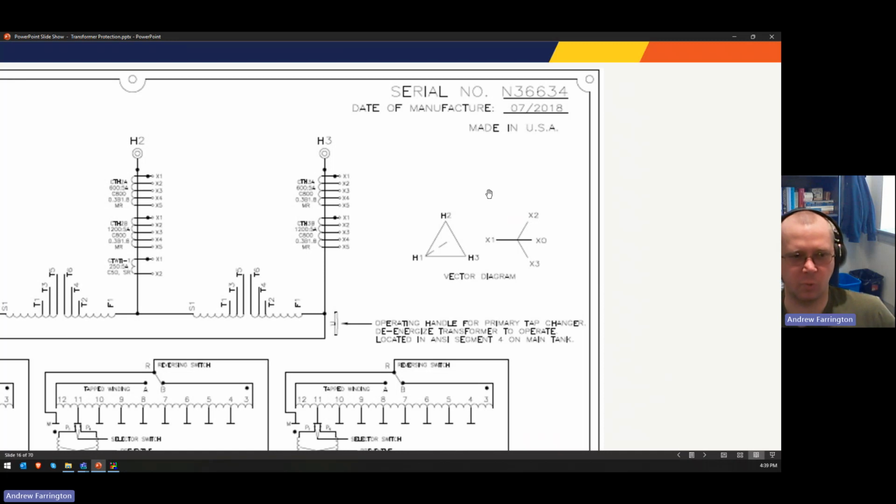I think I've only worked with one utility that had a negative sequence rotation for their system, not a particular transformer or whatever, but their whole system was negative sequence. So they had a 3-2-1 sequence for all of their stuff. So I certainly needed to account for that in the relay settings I provided for them. But I've only seen that the one time. So if not defined, I would assume that the system sequence is positive.